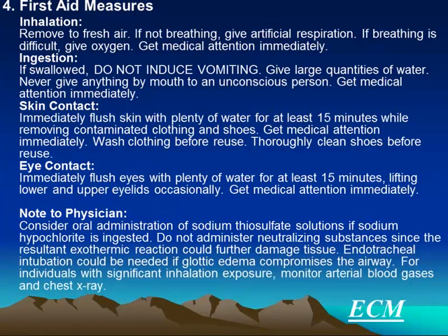And then there's a question on the quiz about treatment for eye contact. I know in dealerships, you may either have the hard-piped eye washes, or you may have the boxes in the walls. The reason those boxes are all the same size is that OSHA mandates you have to have 15 minutes of water at 0.4 gallons per minute. So those boxes are all 6 gallons.